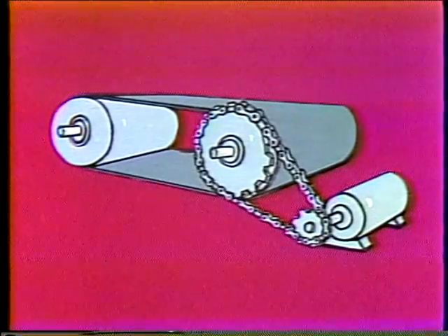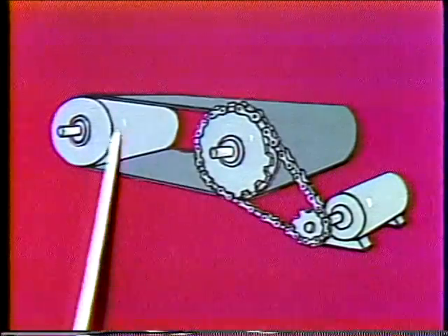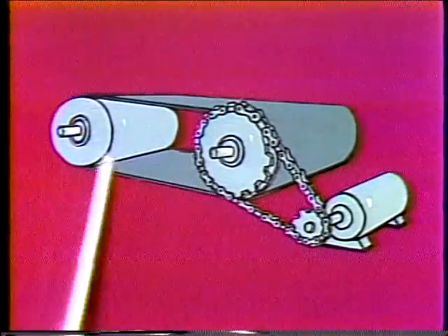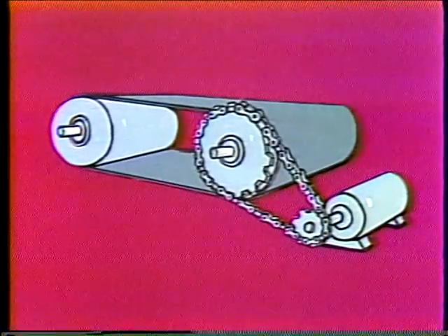What is a belt conveyor? In its simplest form, it's two pulleys around which we wrap a belt, like this, and with some type of drive as indicated. The original belts for belt conveyors were either leather or a woven cotton fabric. Later, this fabric was rubberized to give it more life and make it more resistant to moisture penetration. And then still later, a rubber coating of various thicknesses was bonded to the rubberized fabric on top and bottom.